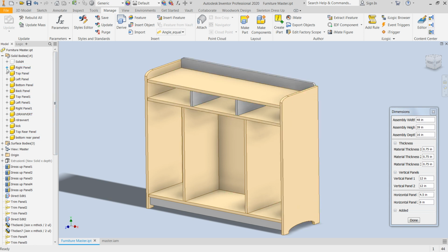They might have a project number like 901 dash right panel or 901 underscore right panel. And depending upon the CAM system you're using, sometimes CAM systems do not like to have dashes or underscores or spaces in their name. So you just have to be careful in what you're naming it. And of course, the whole purpose of that is they would be unique. Everything unique to the 901 project, 902 project, or whatever numbering or naming scheme you might like to use. Obviously, if it goes into Vault, they have to have unique names, and that's why I'm suggesting some sort of methodology that you come up with that will allow that to happen.